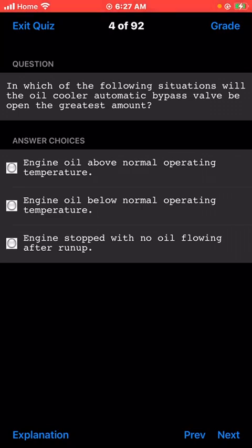Oil accumulation in the cylinder of an inverted inline engine and in lower cylinders of a radial engine is normally reduced or prevented by extended cylinder skirts.